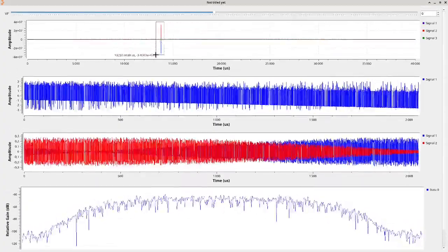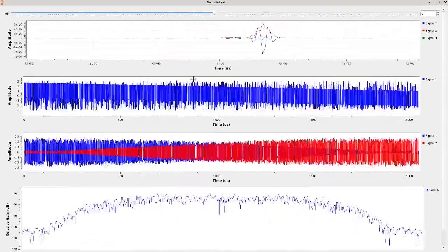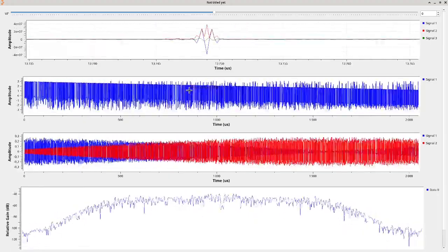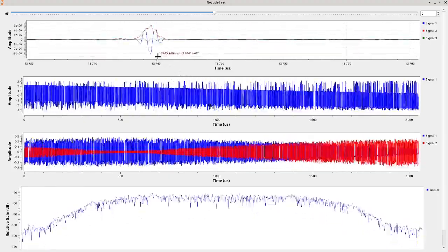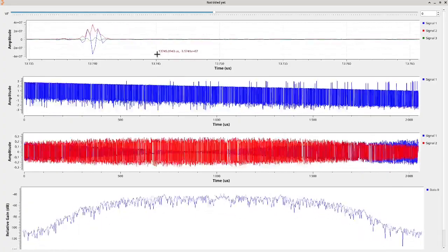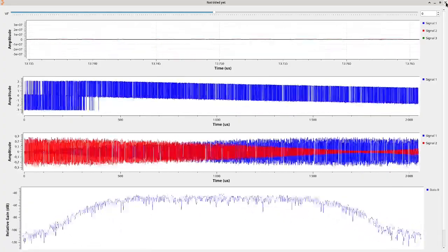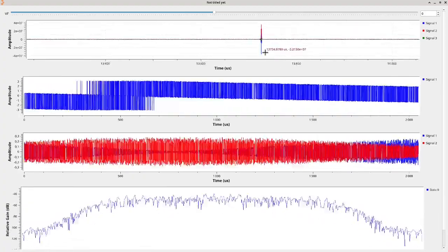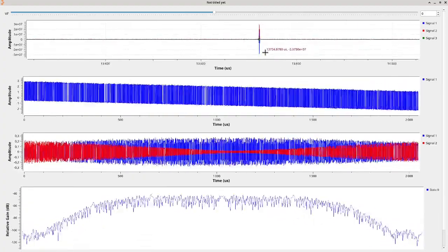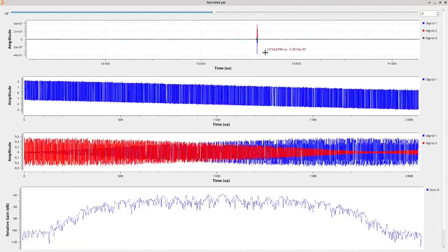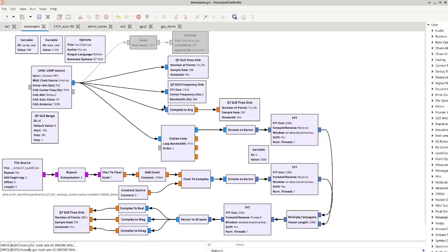And most importantly, we do see that the correlation peak is moving as representative of the frequency offset between the two generators. Most importantly is the fact that this frequency offset is only detected on the code correlation and not on the carrier. Why is this important?